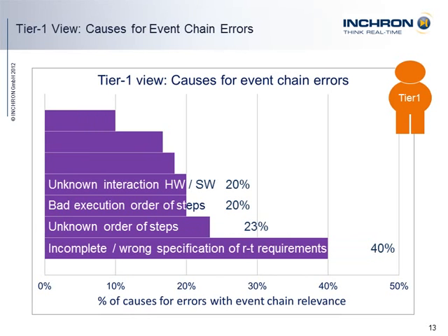The causes for event chain errors within the ECUs are similar. When is a signal detected: at first occurrence, or when the plausibility check has completed? May a single sensor read be lost? What if oversampling is included? The Tier 2 assumes the integrator will take care of the data integrity. Does he also define it as a requirement when integrating his function?